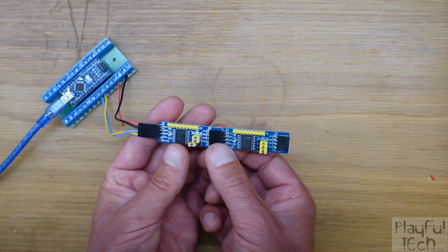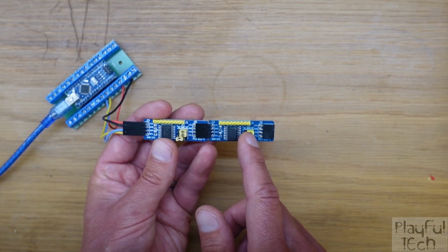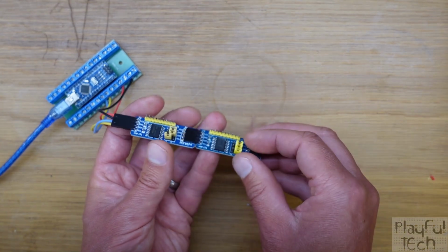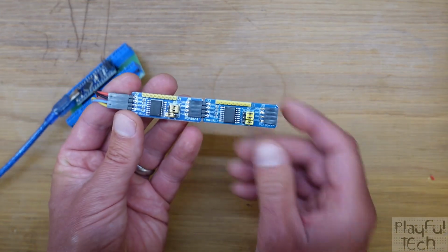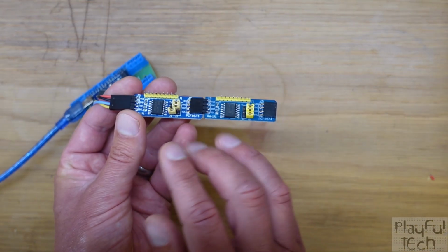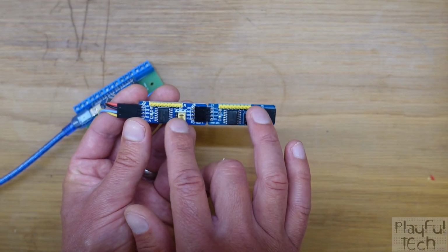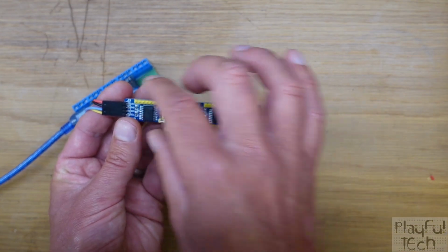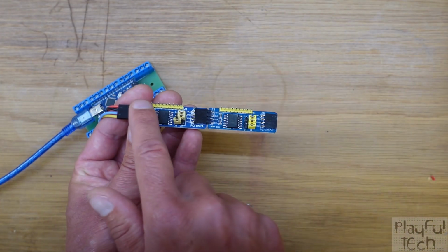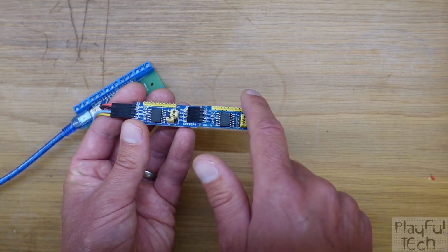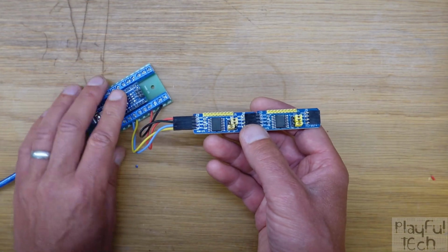All we have to do is make sure that each one of these devices has a different I2C address, which we do by moving the position of these jumpers. Now, there are 3 jumpers and each one can be in one of 2 positions, so that's 8 different addresses. So you can have 8 of these modules chained together on the same bus. Each one gives us 8 more GPIO pins for a total of 64 GPIO pins, which are accessible from the Arduino.